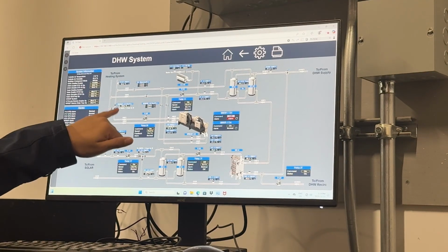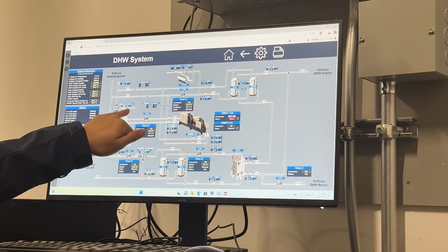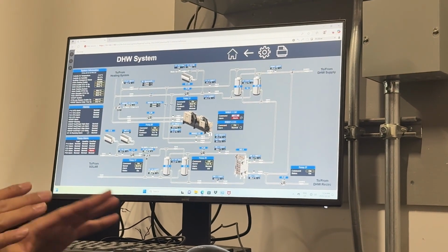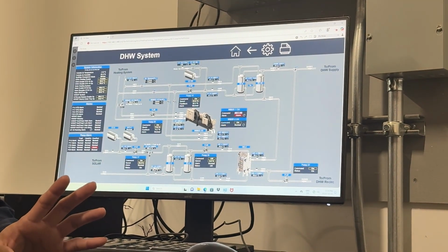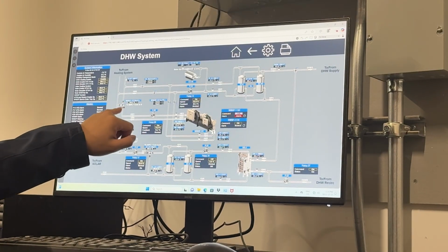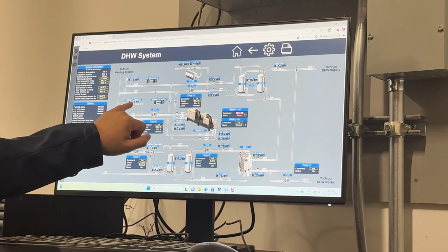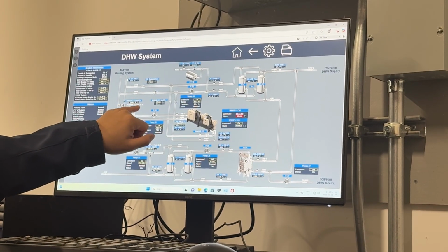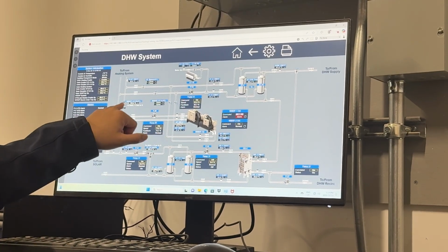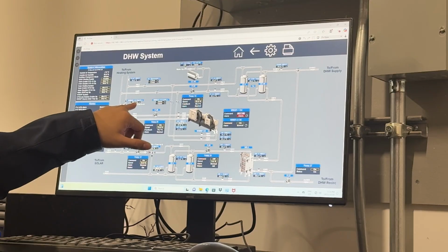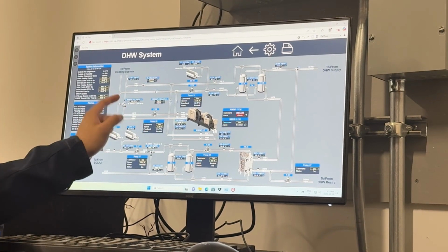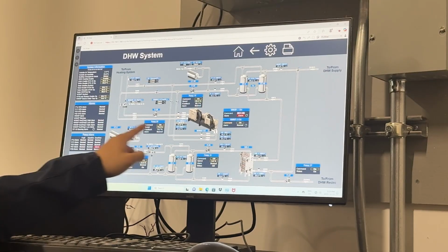Yes, 100% means 100% from common to B, because this hydraulic loop has so many three-way valves, it may get confused how it's open, how it's closed. So that's why we always label which one is A, which one is B, which is common, and all the percentages will say, okay, 100% common to B. Common to B, this is 100% flow. So if it's 0%, it means 0% common to B. Common to B is 0%, so it's full flow.